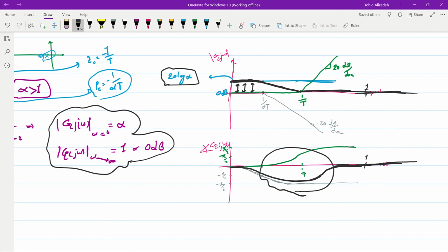So this will help to improve the steady state behavior. At the same time, the transient behavior will remain almost the same, because since we don't change the Bode plot for the system around the crossover frequency, the phase margin will remain the same, the crossover frequency will remain the same, and as a result, the transient behavior will remain almost the same.